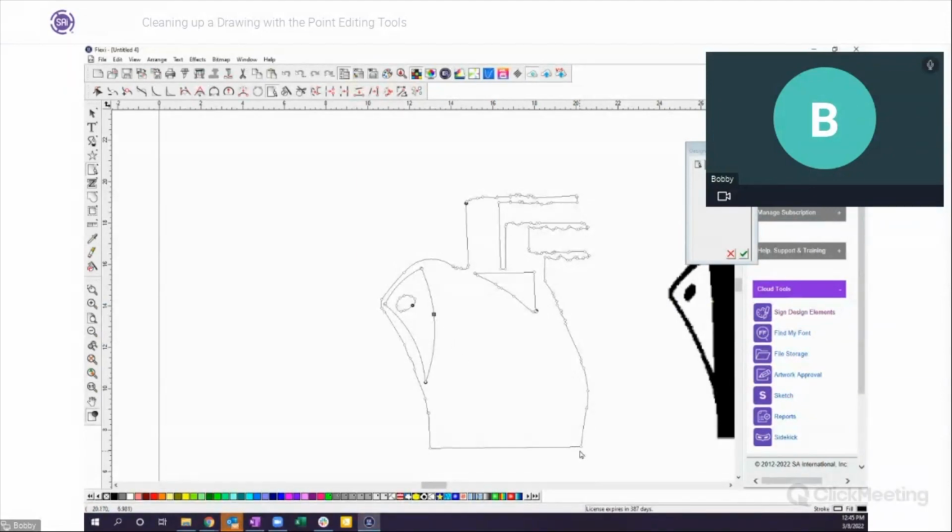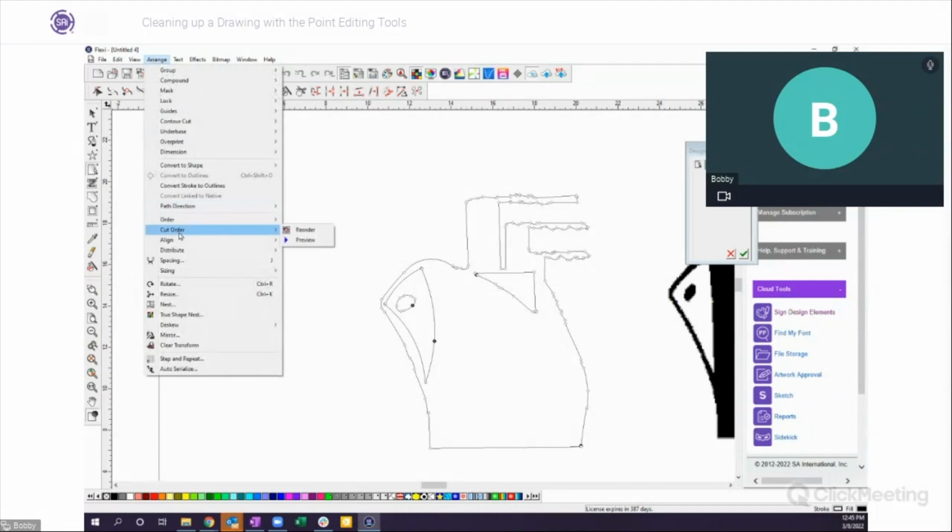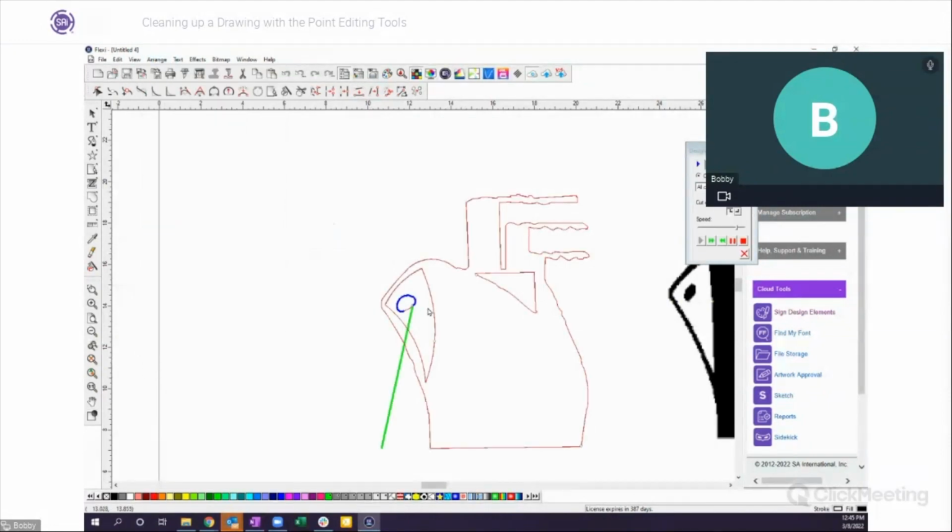Well, actually, you've got to do it one at a time. So click here and then click my check mark. I can click here, click my check mark. I can say I want to start this one up here and then click my check mark. So now when I come back here and preview my cut order, it's starting there. Notice that one started there and this one started down here in the bottom corner.